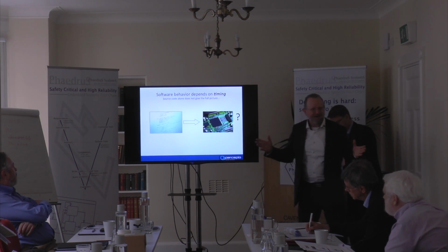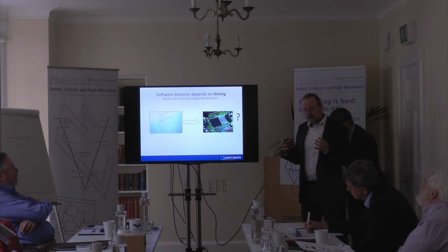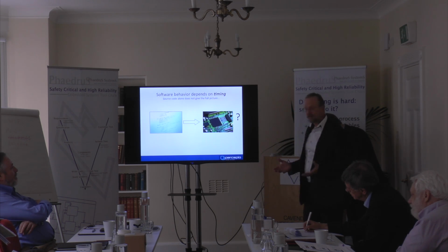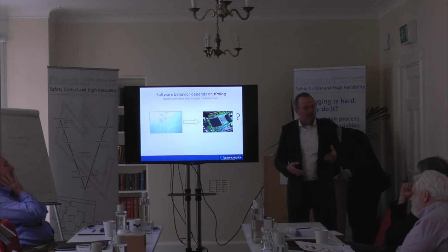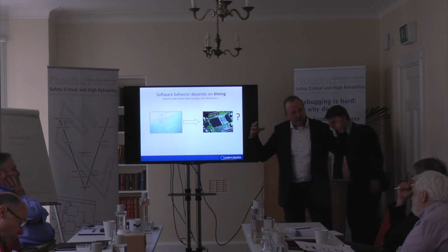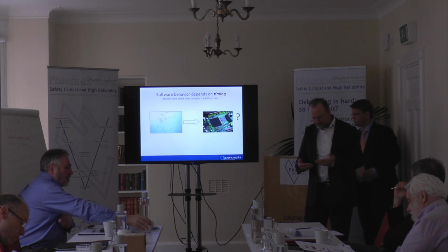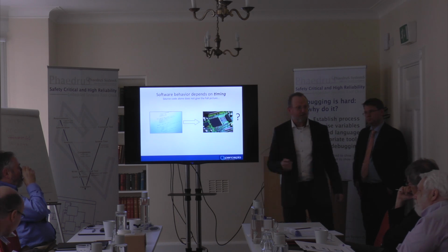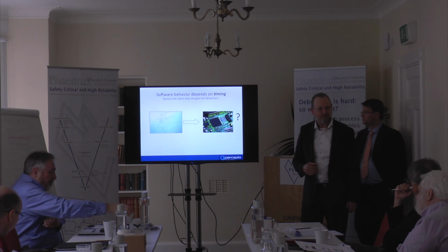As you all know, software is all about timing. In any kind of real-time system, it's all about timing. There's a lot of stuff going on and a lot of stuff coming in, but you always need something to order it, because the CPU only does one thing at a time. More often than not, that's an RTOS in the background.